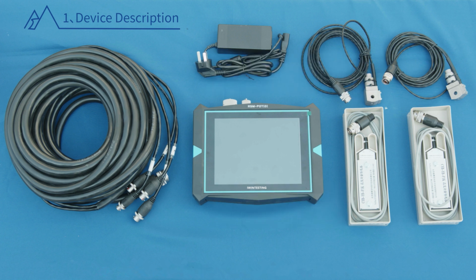By applying a high-energy impact load on the pile top, measure the force and velocity signals. Calculate the integrity and the ultimate axial compressive bearing capacity of the tested pile with the wave theory, or select the pile type and length. Monitor the working efficiency of the pile hammer and the maximum hammer stress on the pile body of the driven pile.